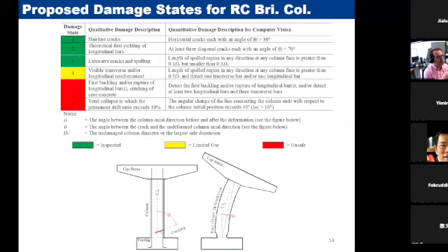I just want to highlight 2 things on this slide. Damage states 1, 2, 3, you'll see I assigned a green color to it, means safe. Damage state 4 is yellow, means only first responders or light traffic can use that bridge. 5 and 6 are red, and they are unsafe, the bridge should be closed. I will provide more justification on these ranges in the following slides. Also I want to mention that theta in this project, which we use to quantify the crack angle, is the angle between the axial direction of the column and the crack, as you can see down on the left picture.